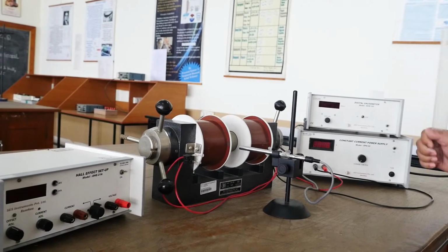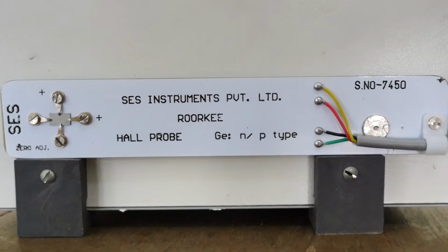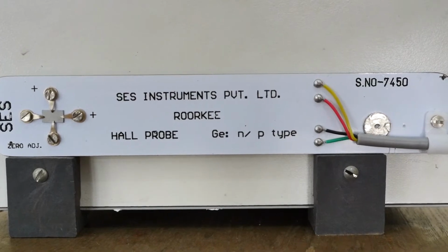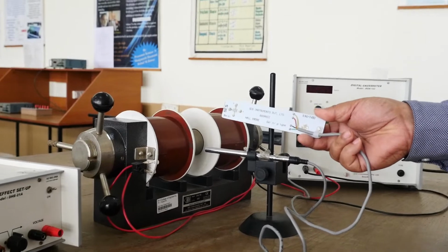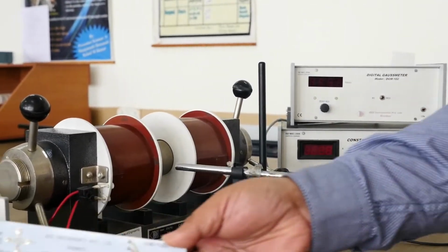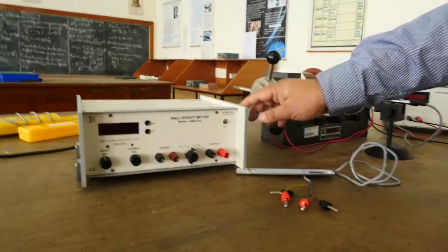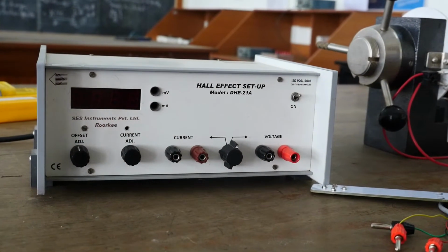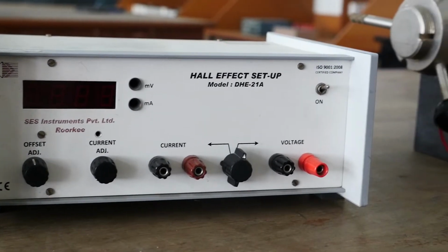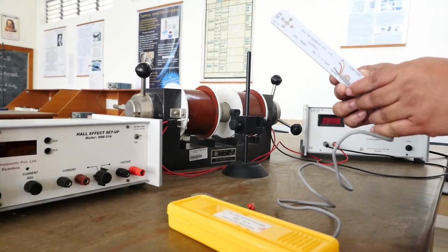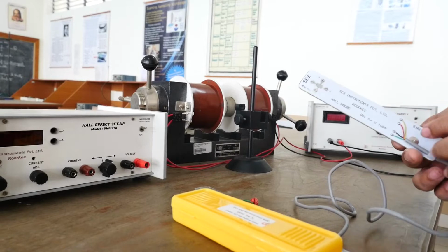we have to use this calibration that has been done to insert a sample. The sample is pasted on this board here, and this sample will be inserted within the magnetic field in a perpendicular condition, and after setting up the connection in this box, which is called the Hall effect setup, we will be monitoring the Hall voltage that is generated across the breadth of this sample, as we have discussed before in the theoretical discussion. To do this experiment, let us understand the connectivity of this Hall sample first.